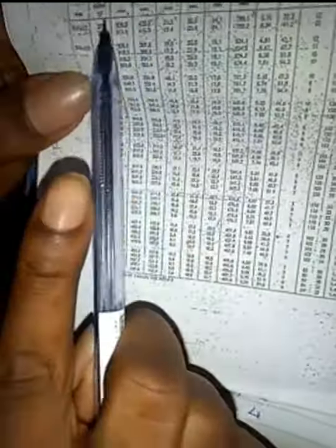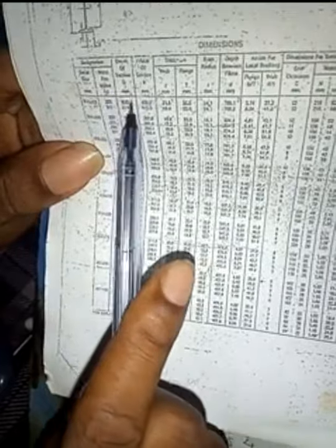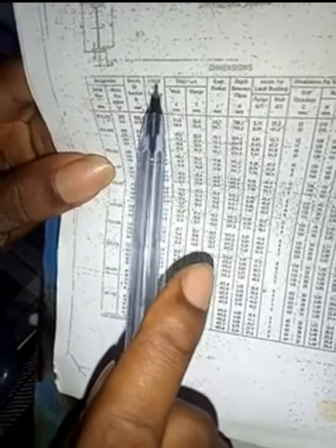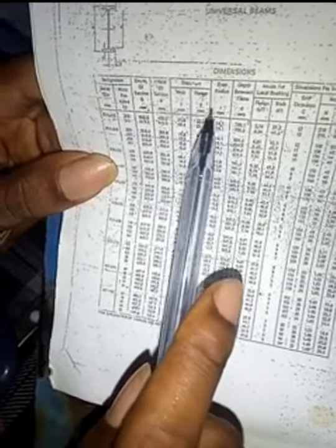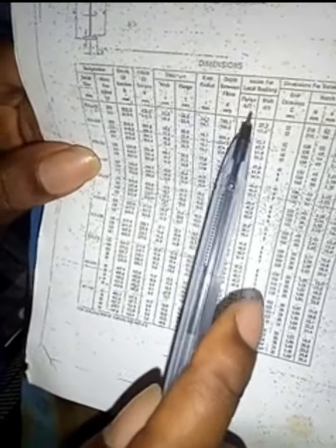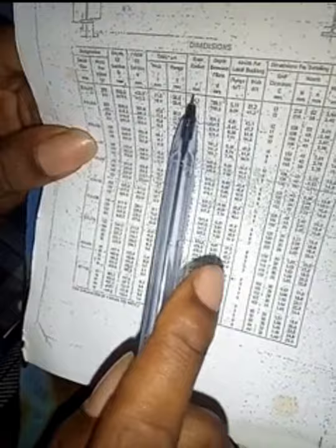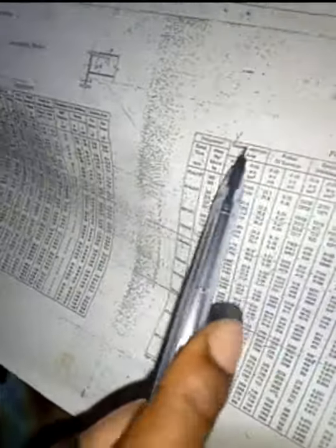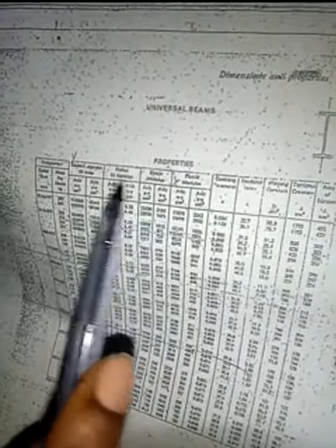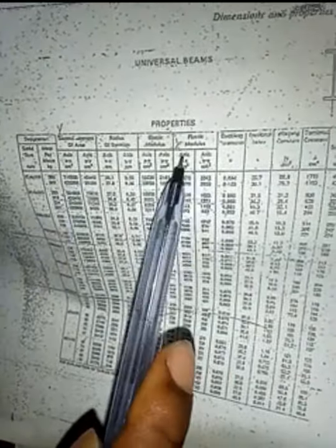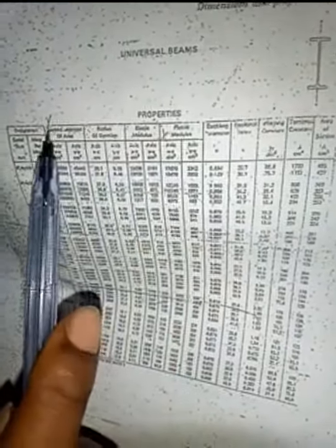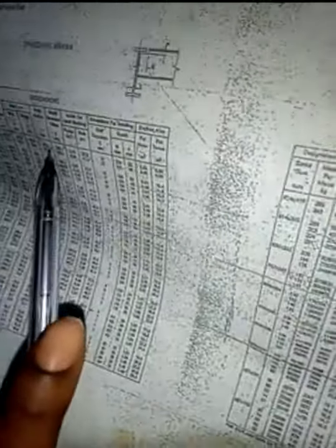So in your section table, you have different things: breadth of section, big B, depth of section, web of section, flange. You have all these things. You have your B over T, your D over T. Then you have your area of section also. I think the area of section is on this side. On this side you have general things like your radius of gyration, section modulus, your moment of inertia. Then I think area is somewhere here. So you are going to be getting these things.